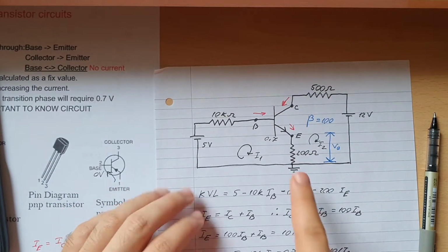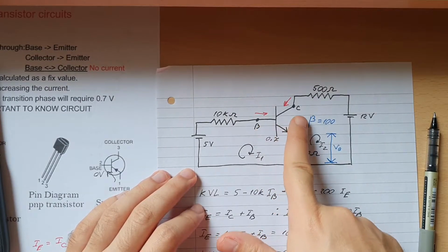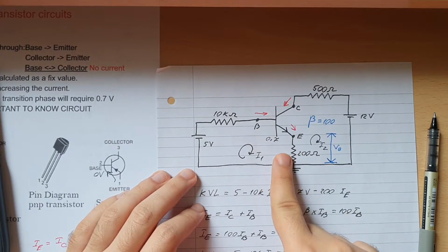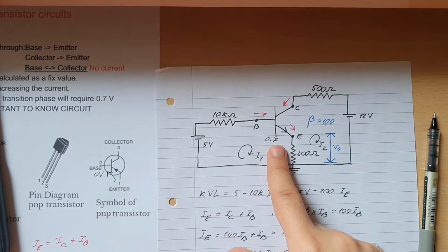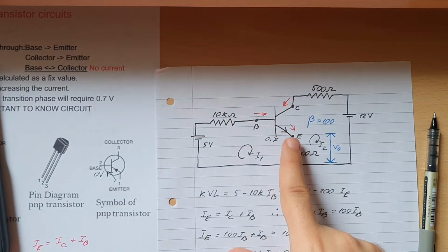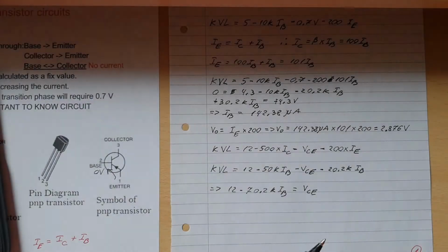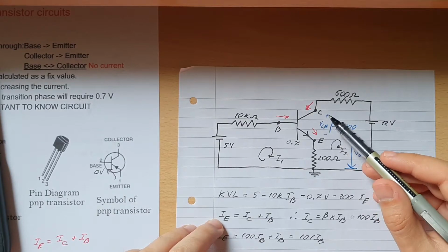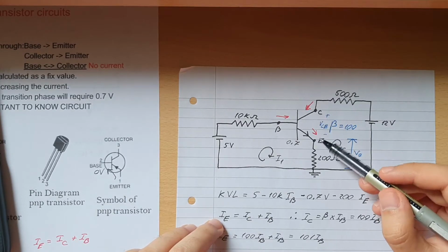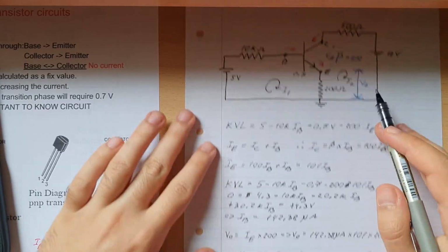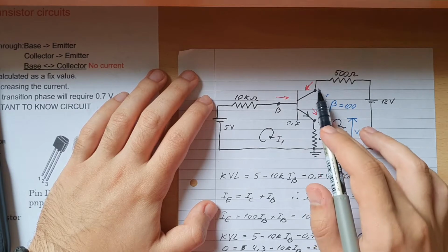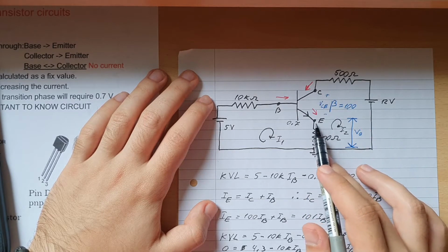Another interesting thing is that each section has its own voltage. So VBE is 0.7 volts for most transistors. And again, remember that the 0.7 can be interchanged as well. Some transistors may use 1 volt. Sorry, I think the recording cut. So I was saying some problems ask you to find VCE as well, which is the voltage between point C, the collector, and the emitter. And I was doing the formula here. You can apply Kirchhoff's voltage law, and that will be simpler because you already know the current through IC and you also know the current through IE.